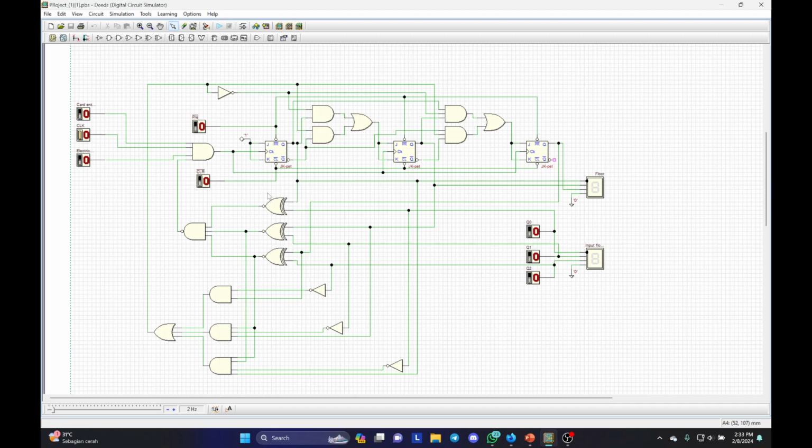In contrast, if the output of our comparator is 0, our XNOR gate is 0, the comparable NAND gate will output 1, indicating that the current floor of the lift and the floor inputted is not the same, thus continuing the process of our lift. If the lift is going up, it will continue to go up. If the lift is going down, it will continue to go down.